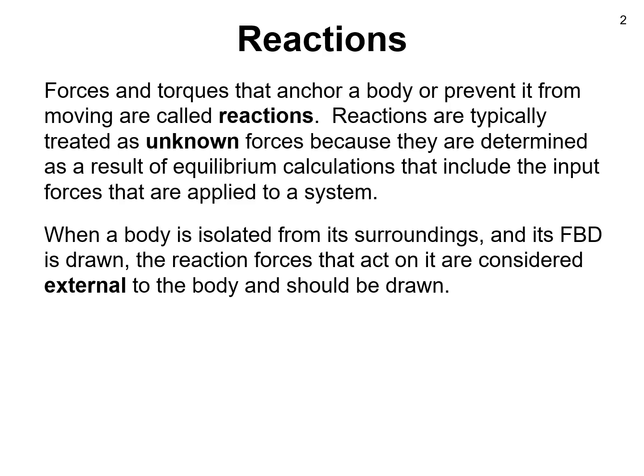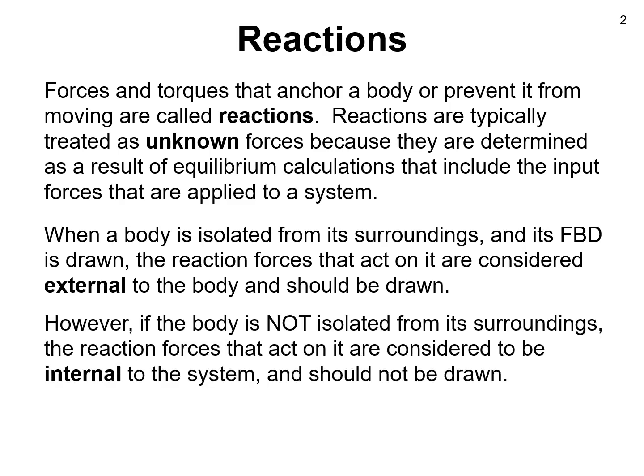When a body is isolated from its surroundings and its free body diagram is drawn, the reaction forces that act on it are considered to be external to the body and should be drawn. However, if the body is not isolated from its surroundings, the reaction forces that act on it are considered to be internal to the system and should not be drawn. And we'll see this through our examples later.